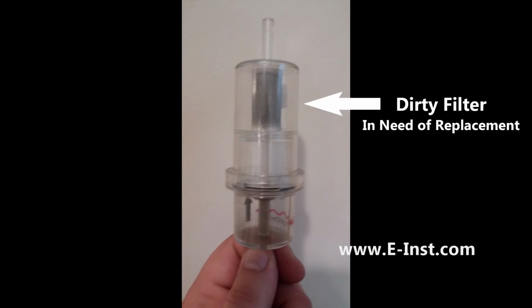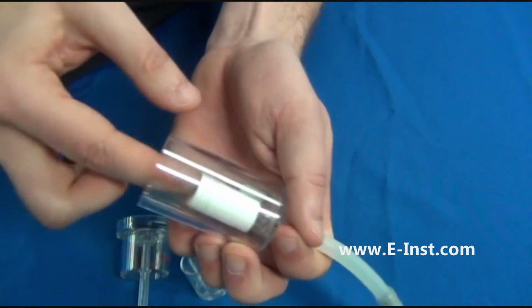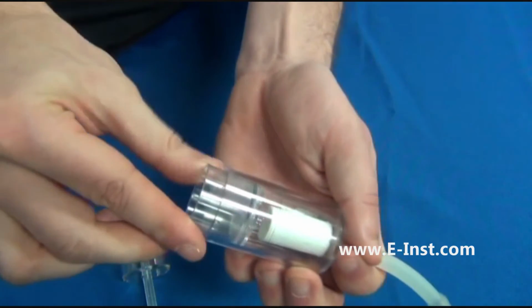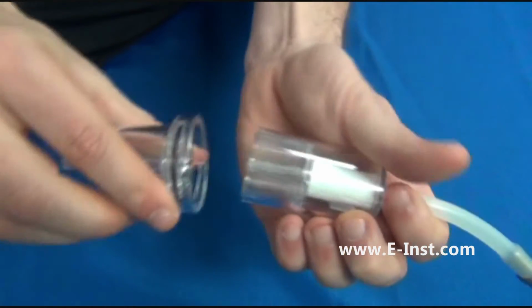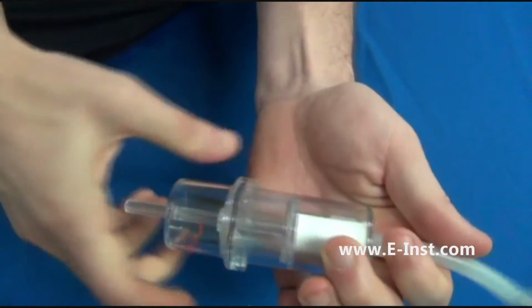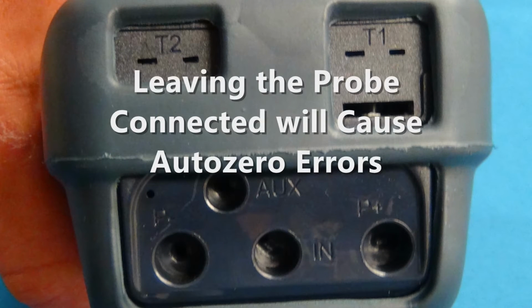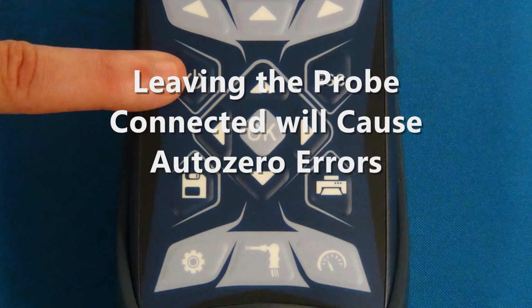inside. If the filter has any cracks or a heavy buildup of dust or particulates, replace it before performing any combustion and emissions tests to prevent any of the combustion byproducts and particulates from getting pulled into the instrument while maintaining a proper gas flow rate. Make sure that none of the probes and hoses are connected when the instrument is turned on.